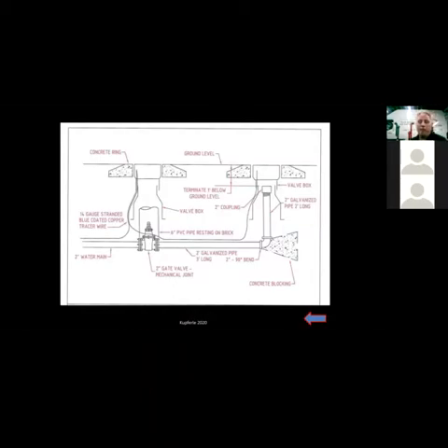This is a gate valve. So if I have a gate valve in one 5 1/4 inch valve box, and then I have an attachment for a 2-inch riser in another valve box. So it's a 2 valve box design. Now, if I'm in warm climates where it's not quite as cold or the depth of bury isn't as deep, I could have a curb stop in that first valve box, or I could have a ball valve. So usually I see 1 of 3 things in that first valve box: usually a gate valve, a curb stop, or a ball valve operating nut.